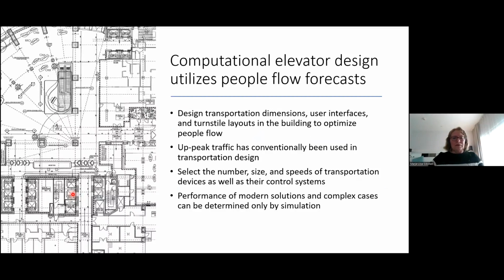So we design how many elevators we should have, how many elevator groups we should have, how many escalators, and how many turnstiles, and then we place them in the architect drawing. And it's always a compromise between the space and price and service level. So it's a complicated design phenomenon that has to be repeated many times before the building is ready.